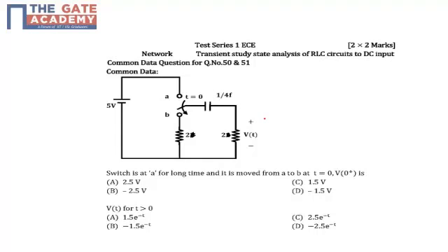So we know that the circuit has said that the knob T is connected to the point A, and the circuit is in steady state. At t is equal to 0, we have changed the knob from position A to position B. Before this change has occurred, my circuit is in steady state, and we know that the capacitor opposes the sudden change of voltage. So let's draw the steady state circuit at t is equal to 0 minus.